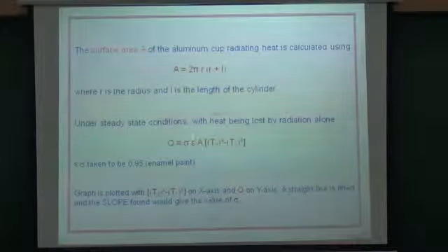We have to connect the banana terminals to the heater through the constant current source. The current that we have to set is 200 milliampere. Then connect the DC differential amplifier terminal I1 to the RCA socket of the thermocouple on the box. We have to choose the amplification factor of 100. We then take a digital multimeter in the 200 millivolt range and connect it to the output of the DC differential amplifier.